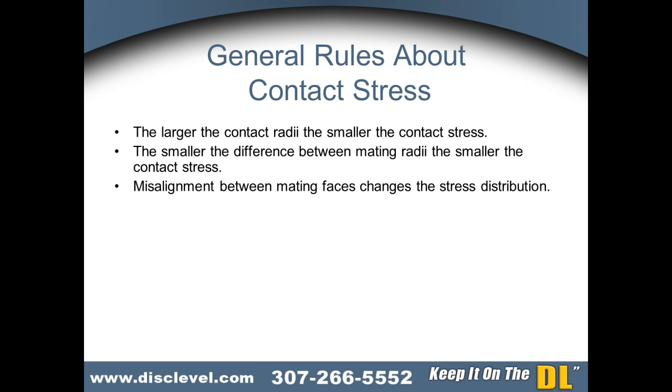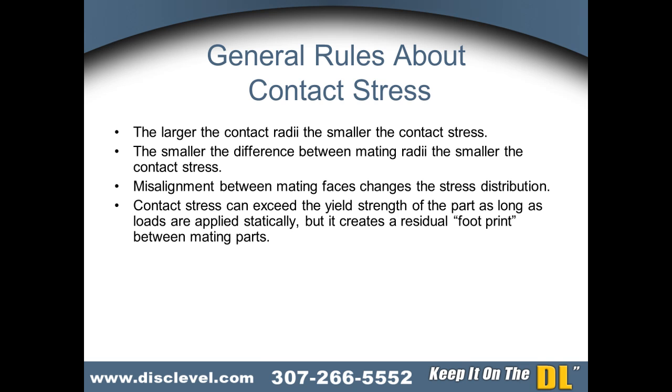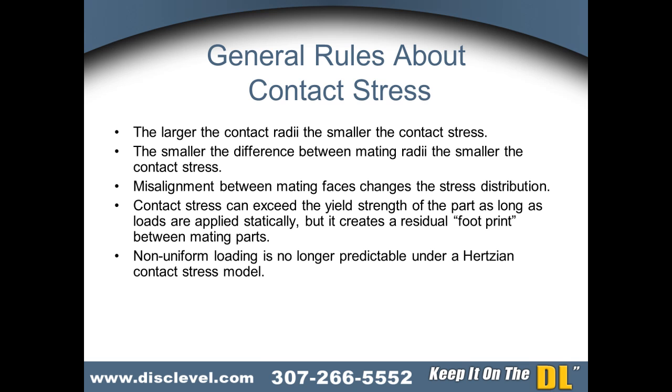Misalignment between mating faces changes the stress distribution. Contact stress can exceed the yield strength of the part as long as loads are applied statically, but it creates a residual footprint between mating parts. Non-uniform loading is no longer predictable under a Hertzian contact stress model.